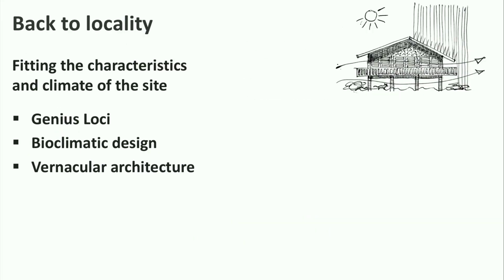For instance, in the tropics, where temperatures are always high, vernacular architecture makes optimal use of the cooling capacity of wind by creating air permeable facades and floors. But roofs need to be suited to withstand heavy rainfall, and buildings should be put on poles to keep out animals and also to create a maximum air current.